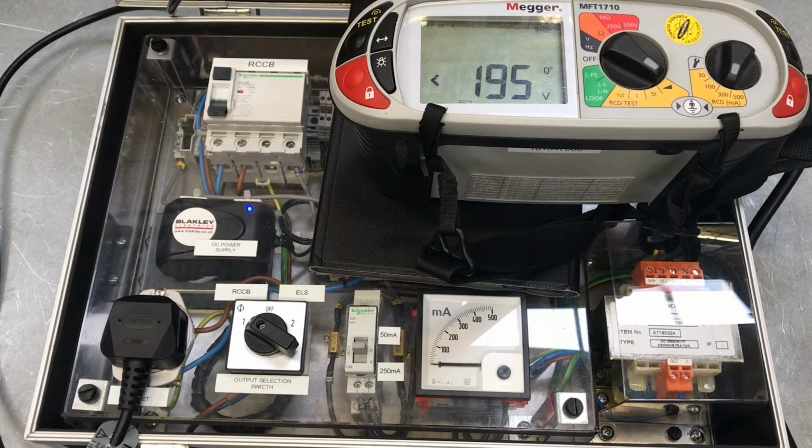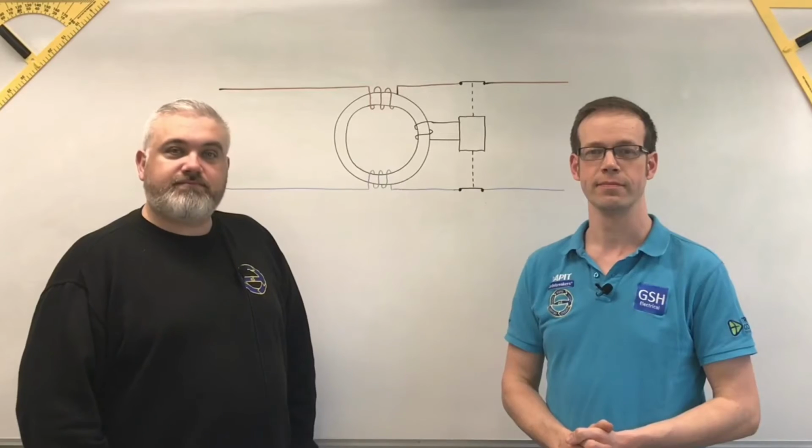But it's well worth noting, I always say to guys, if there's 2 regulations you learn, 132.16, your alterations and additions, bonding, imperative for safety, but also Appendix 5, external influences. I work on a railway that goes parallel with the sea. So if you come onto my railway and you select and erect some conduit and trunking, it's either going to be GRP or stainless, because when you look into the detail of external influences, it will actually describe salt mist testing and pollution categories, which as sparks we don't get involved with. But when you start looking at working from the regulations, you'll find your knowledge will immediately start opening up, and you'll actually provide a far better quality product for your clients. So it's just something to be aware of.